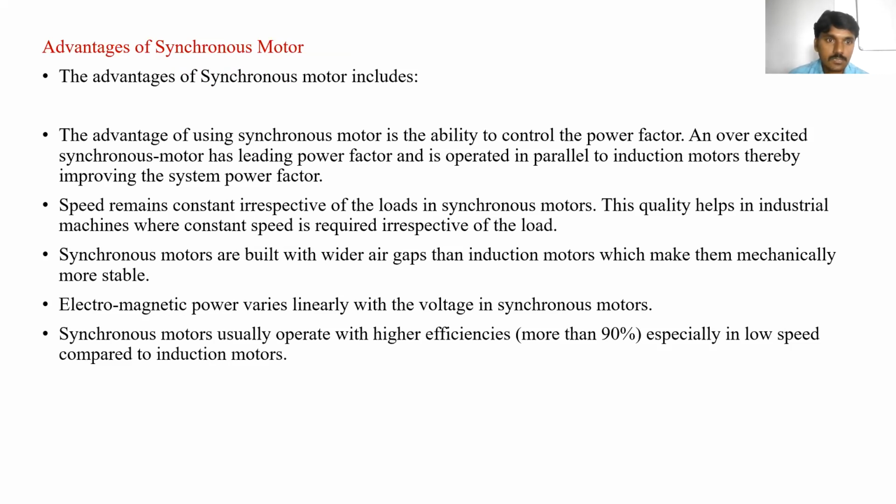An over-excited synchronous motor has a leading power factor and is operated in parallel to the induction motor, thereby improving the system power factor. Speed remains constant irrespective of the loads. Okay, the speed of the synchronous motor remains constant irrespective of the load. So this quality helps in industrial machines where constant speed is required irrespective of the load.